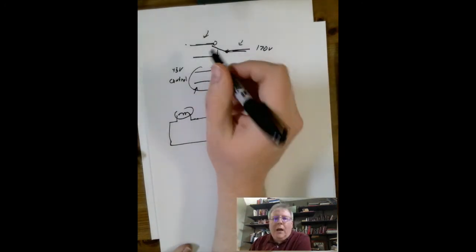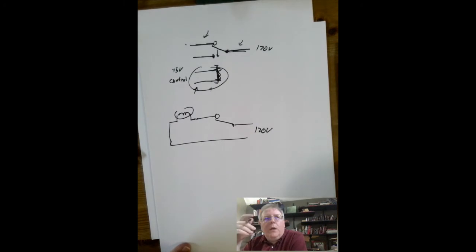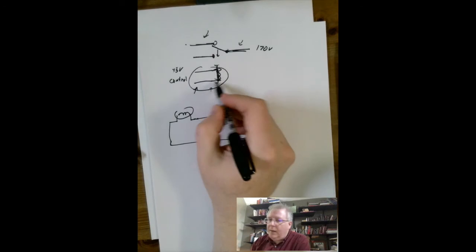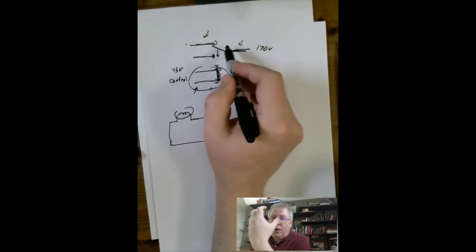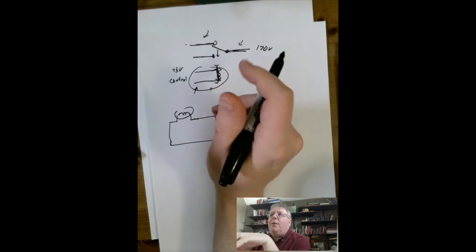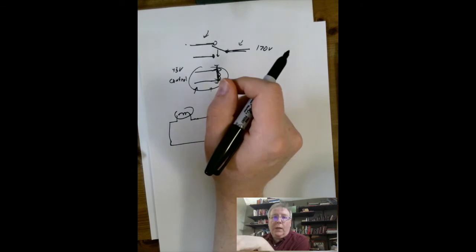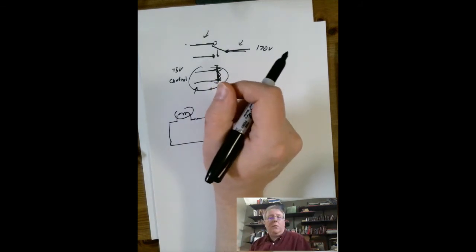But these are still used all the time in your car. If you have, for instance, your power windows, the switch that controls the power windows controls the electromagnet here, and then the actual power window is a pretty hefty motor which runs through a relay. And so, in fact, you can hear this clicking sometimes in your car. If your power windows aren't working, you might hit the button and hear a click, but the power window doesn't move, and that means you need to replace a relay.